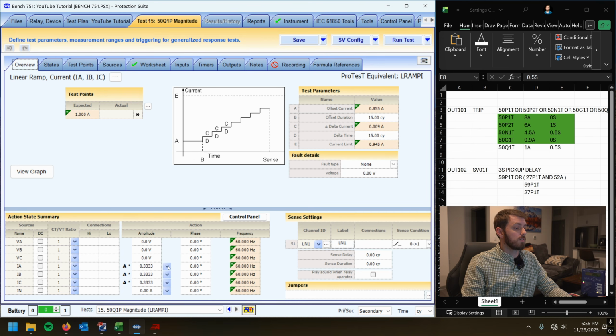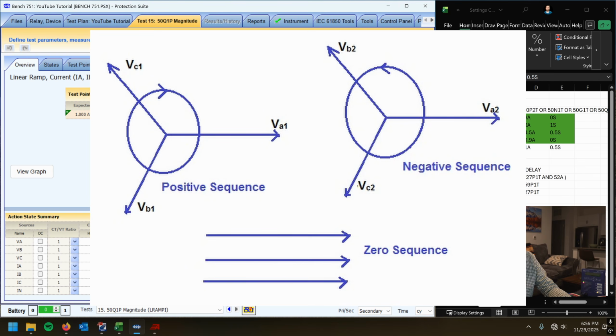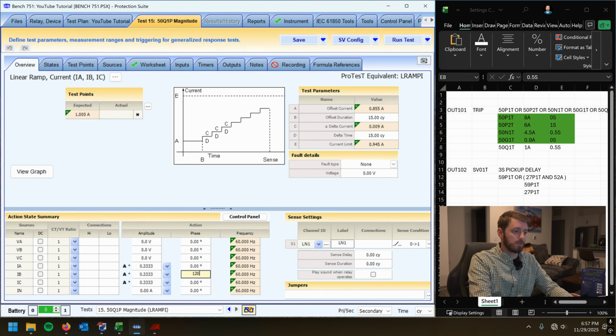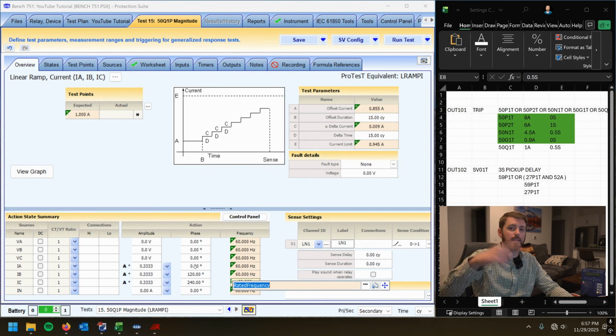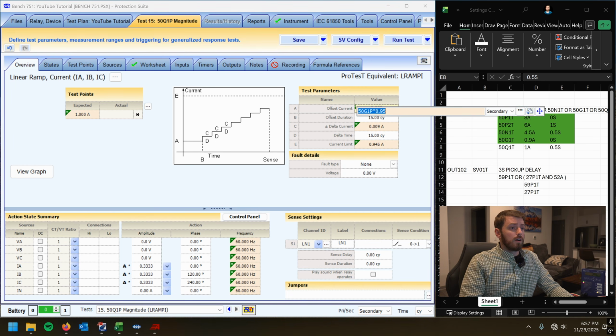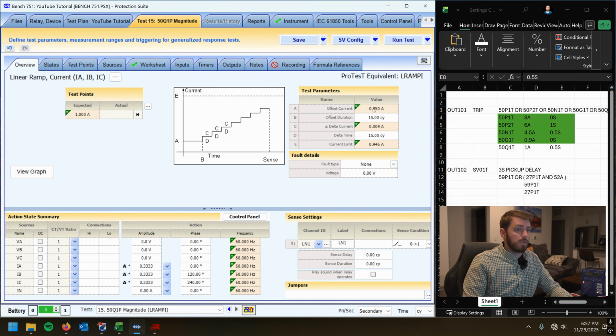That looks all good. And now, instead of this being zero sequence, I want it to be negative sequence. So here I'm going to do 0, 120, 240. So I'm rotating clockwise instead of counterclockwise. All this should be fairly similar. Going to be happy with that.